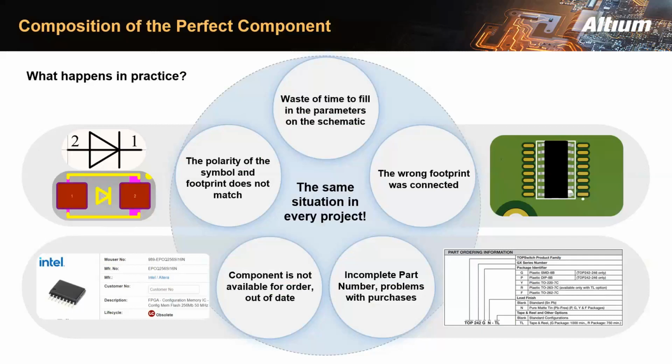with the proper values. Also, when pursuing rapid creation of a schematic, designers may not associate footprints to symbols as they only need to create a schematic for a deadline. Incorrect footprints can be associated with components already in the schematic, leading to potential errors. Most often, these result in a polarity mismatch between the symbol and footprint, or the wrong footprint has been defined and the problem is detected